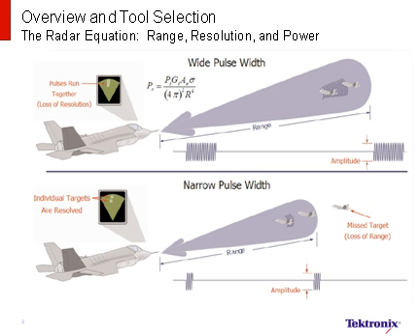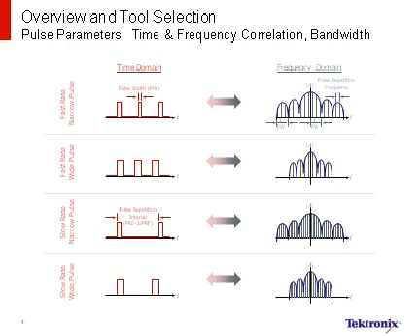With all other variables remaining constant, a narrower pulse width uses less power and can significantly impact the effective range of the radar. What's not shown is the pulse repetition interval, which needs to be considered to make sure that you're not talking when you should be listening. Thus, the operational modes of radar transmitters often have the most basic controls of pulse width and repetition frequency, or PRI, to allow for variable target tracking and range resolution.